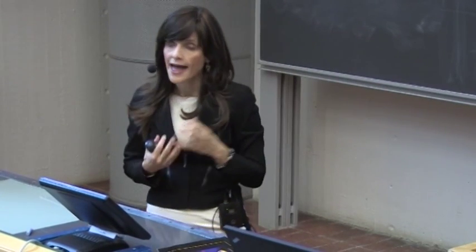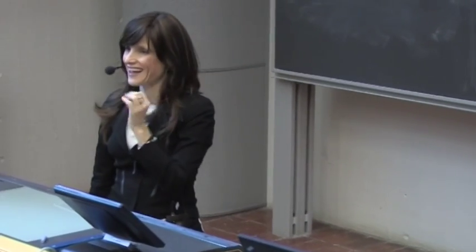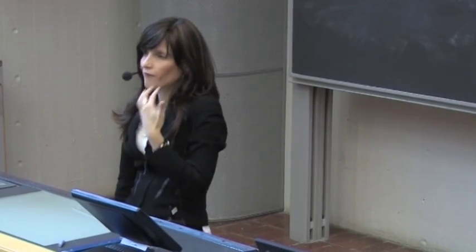So there are many, many problems where this model appears, and therefore there's been a lot of work on this problem. And in fact, a lot of the nice subspace ideas that some of you are probably familiar with, like MUSIC and ESPRIT, these types of ideas, actually originated from studying this class of problems. But all of these nice methods require sampling at the Nyquist rate. Now, when I say Nyquist rate here, it's worth taking a second and thinking about it. The Nyquist rate of what?